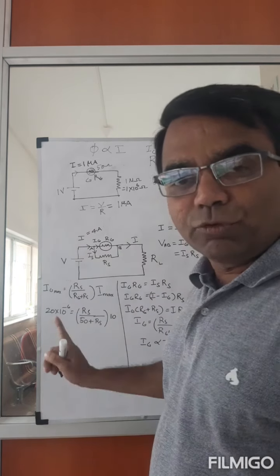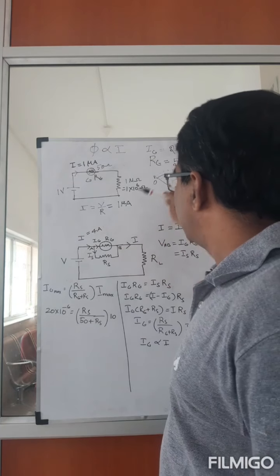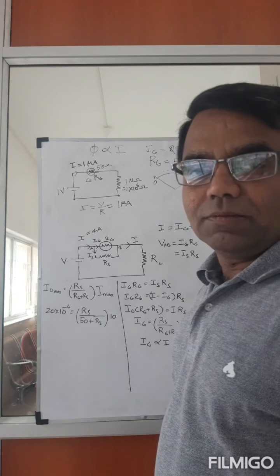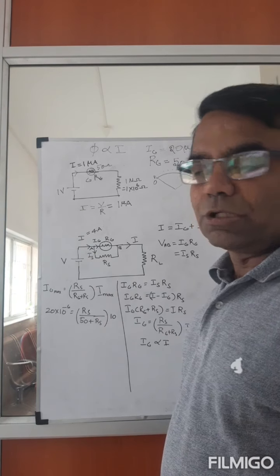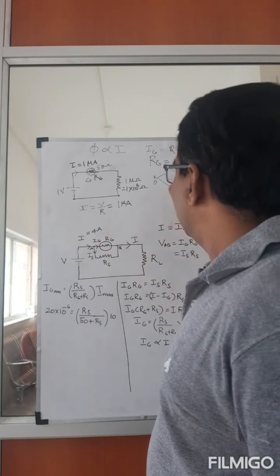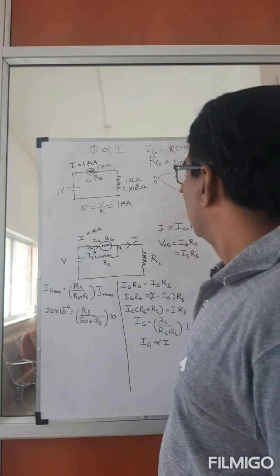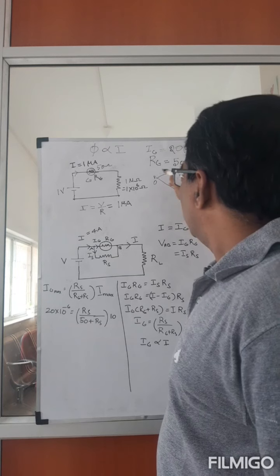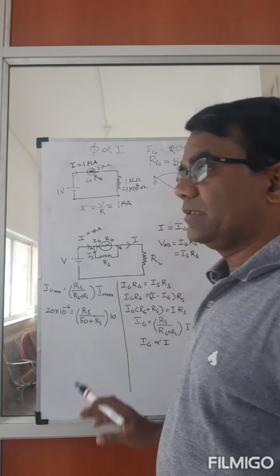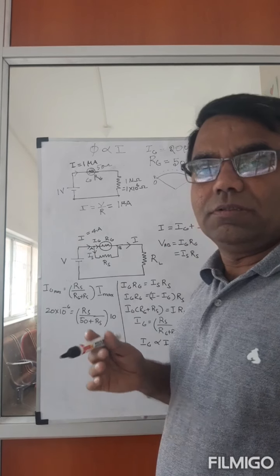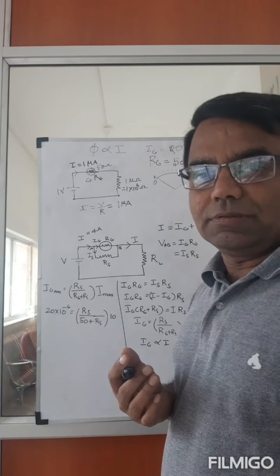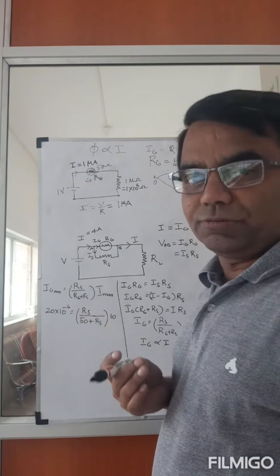Now if only 4 amperes is flowing through the circuit, the galvanometer will show only 40% of the deflection. So this way, even though the galvanometer can allow only 20 microamperes, you can make it measure more current. I hope this is clear to you.